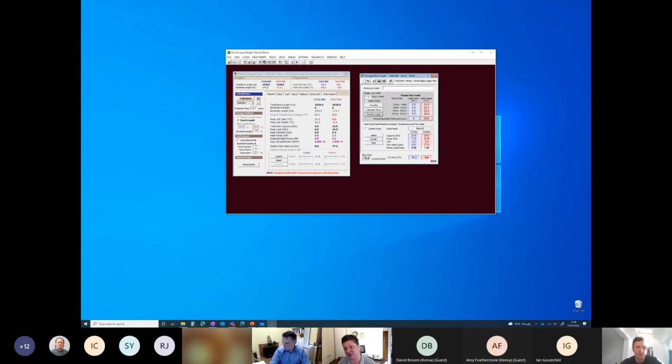When we hit update on this, it gives us a summary here, which is like a design day, worst case day. And it also gives us this full load hours, which is a useful quantity. If you're new to the industry, divide your annual kilowatt hours by the peak, and it will give you a number, which is the equivalent full load hours, we call it. Get a feeling for that. It's a really useful quantity.